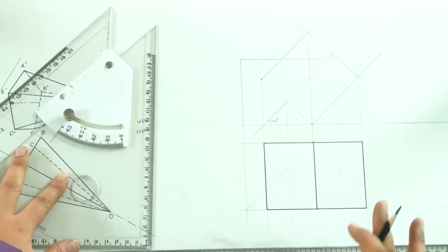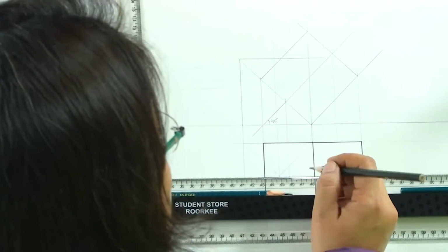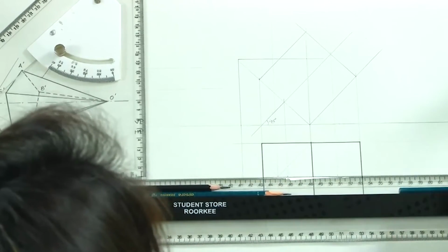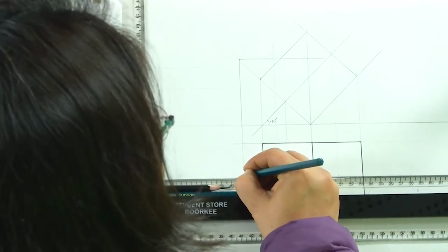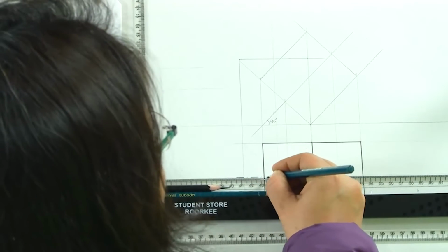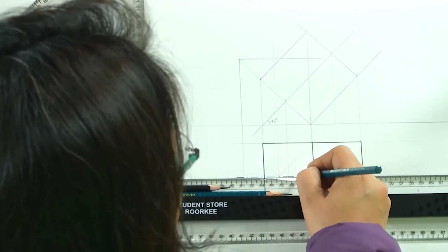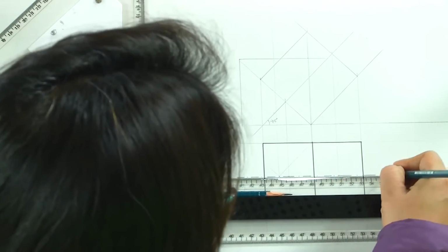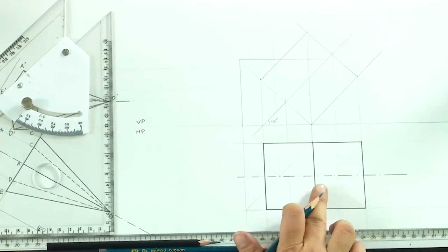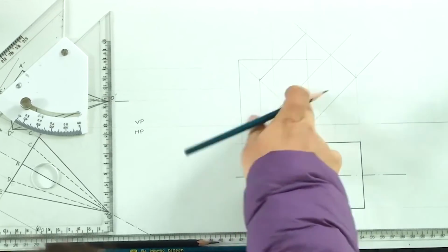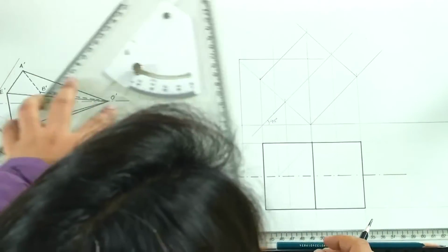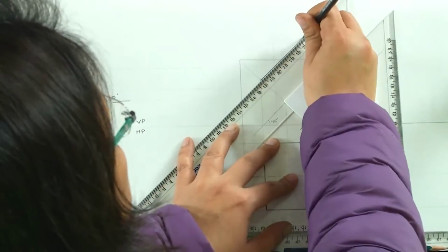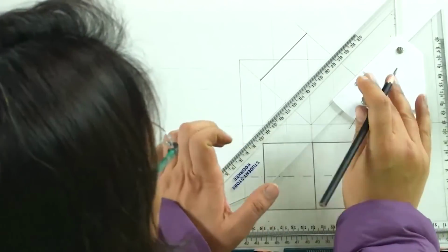These are the visible edges, and we have an axis which is passing through this. So it is not visible here, but then it clearly shows that this axis remains parallel to the VP. And let us now darken the elevation, which is inclined.